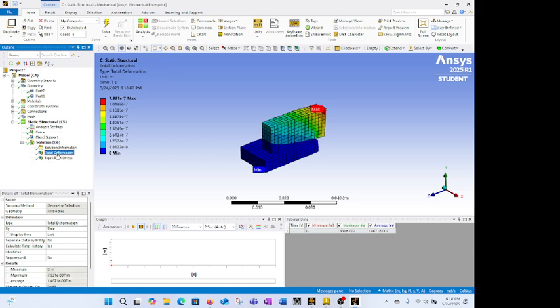Okay, so a very quick video. You can draw in Design Modeler, you can draw in Inventor or SolidWorks. If you're going to have two different materials, make an assembly file, send it out as a step file, bring it in here, assign your properties, create the mesh, assign your structures, your moments, your forces, fixed supports, establish what you're going to look at for solution.